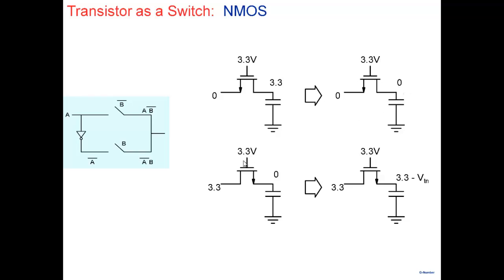On the other hand, if let's say this particular capacitor was at 0 volts, or logic level 0, and we connect it through a switch again, and we now want to pass a 1. We want to charge it up to 1, charge it up to 3.3 here. Now what happens is, note that when you want to charge, this acts as a source here.